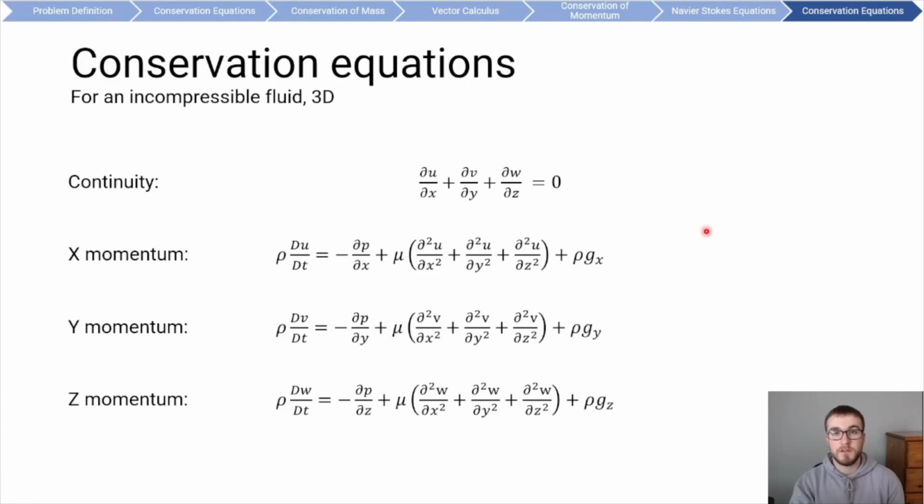When you're in your CFD software and you click initialize, what you're doing is setting an initial value for velocity and pressure in each of the cells. What the SIMPLE and PISO algorithm does is iterate through the solution and check if continuity is satisfied, until eventually continuity is satisfied. And that's what's done by your CFD code when you're solving your CFD solution.